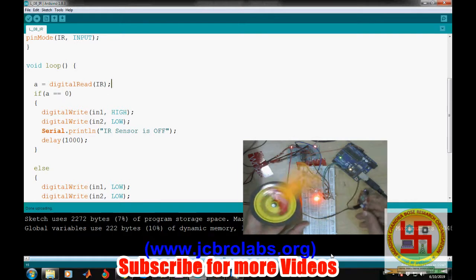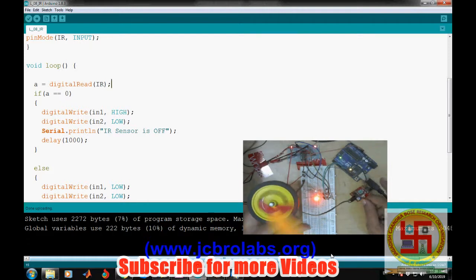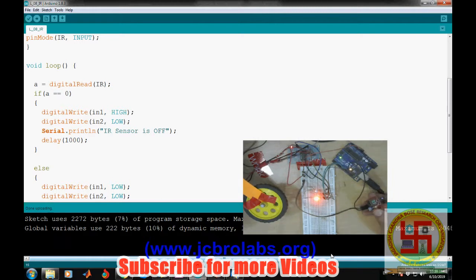Okay, one more thing with this IR sensor, if you are trying to use this particular sensor module in front of sunlight, then your sensor module may not work properly, because there is a lot of stray IR radiation in sunlight, right? So your photodiode may detect the stray IR radiation as radiation coming from the IR LED. So in that case, if you want to use this sensor in an open field, you may have to recalibrate the sensor. In order to recalibrate it, you just have to change the reference voltage value, which can be changed from this potentiometer. That is all you have to do.